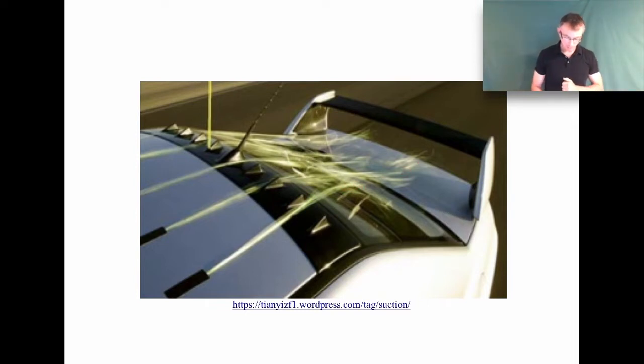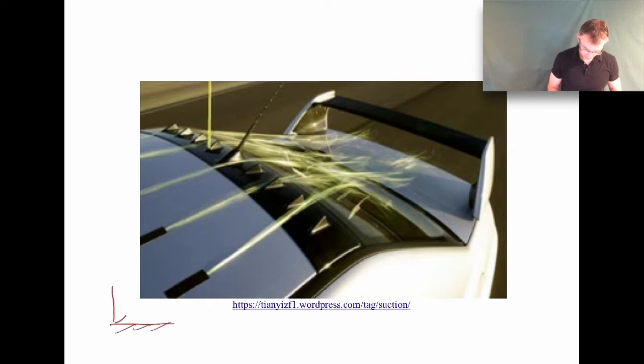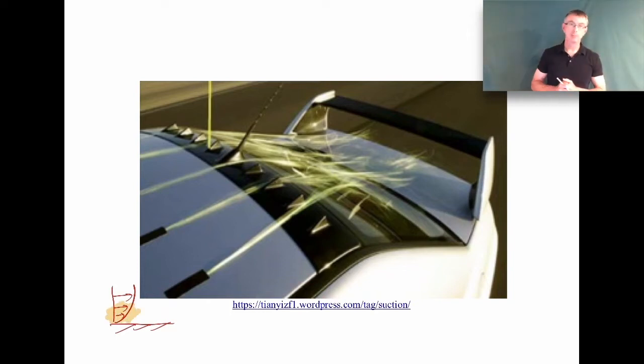The purpose of these vortex generators is to control the boundary layer. They do what's known as re-energizing the boundary layer. As you already know, the boundary layer has low momentum air to it. Let me sketch this out for you. So here's our boundary layer, has this kind of profile. Close to the surface down here, the boundary layer has a small velocity and thus small linear momentum.